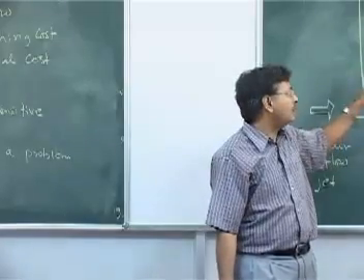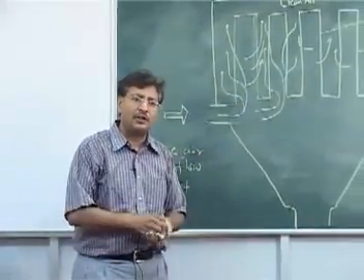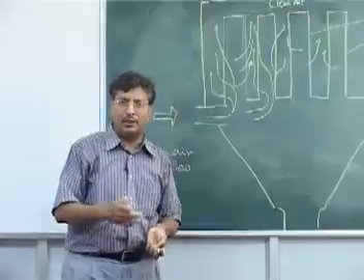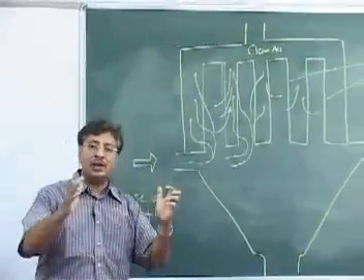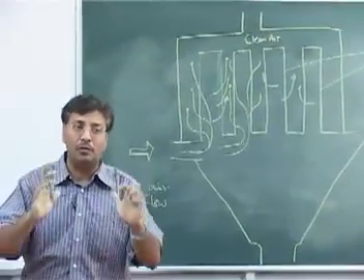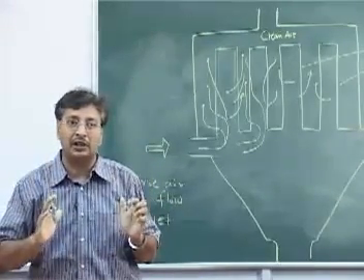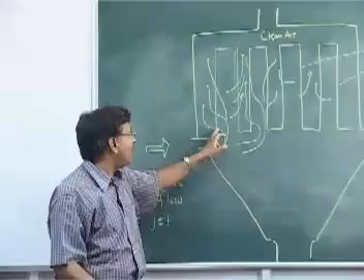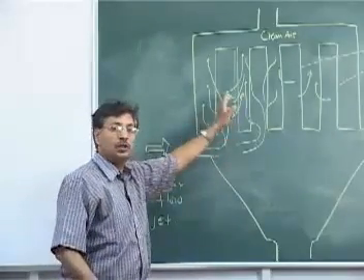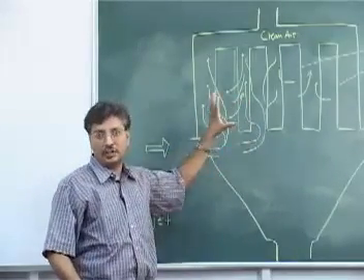The order of the pressure drop difference is so high, I don't remember the numbers. In the ESP there is no obstruction to the flow of air; it just travels as if in a duct. Here every little thing has to go through the filter, so the pressure drop is enormous.